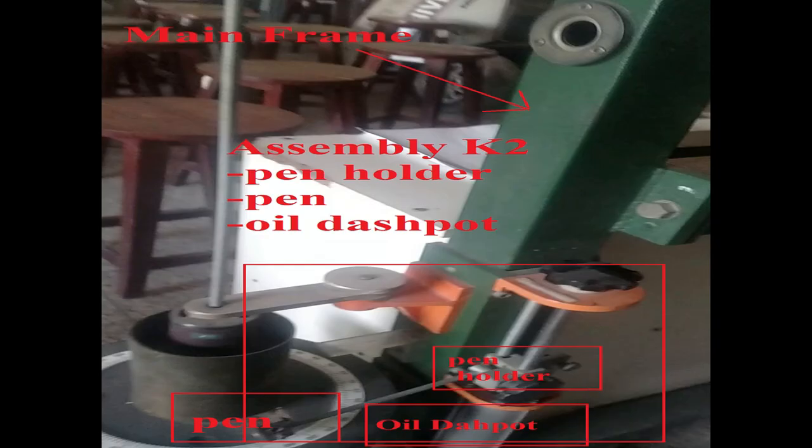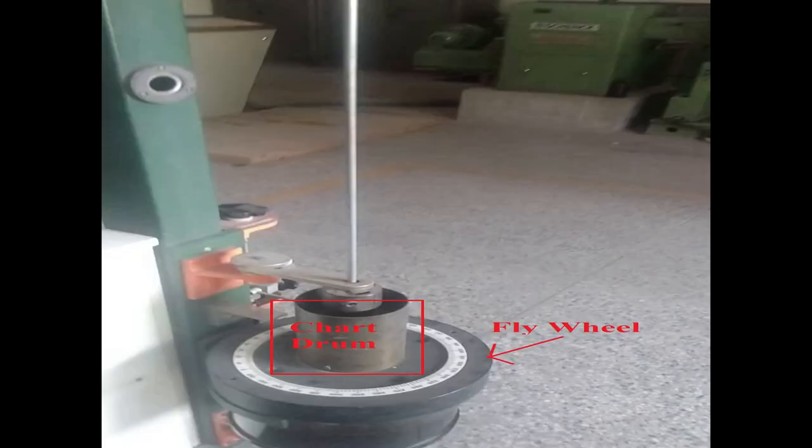After selecting and fitting a suitable shaft, the length of the shaft between the two inside chuck faces should be noted, in addition to the shaft diameter. The rate of descent of the pen in millimeters per second should be measured by timing the descent of the pen over a fixed length of paper by means of a stopwatch. The torsional oscillations of the system for any chosen damping area can then be recorded. The pen should be raised to the top of the chart drum and the rotor rotated through a suitable angle, about 20 degrees, and released.